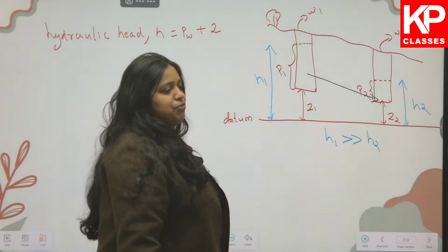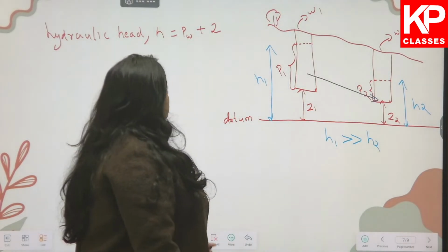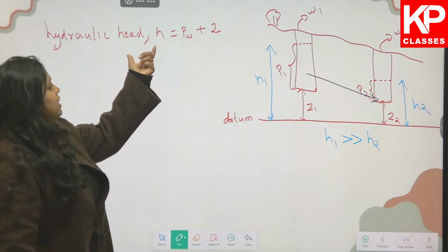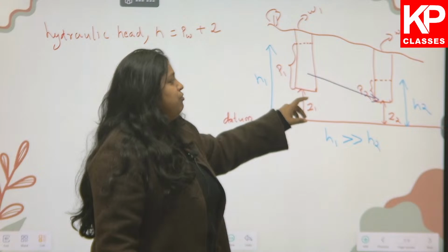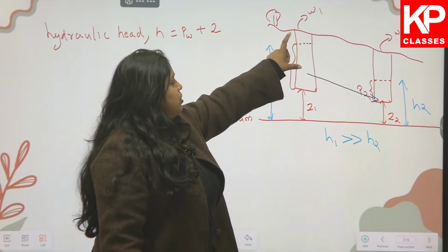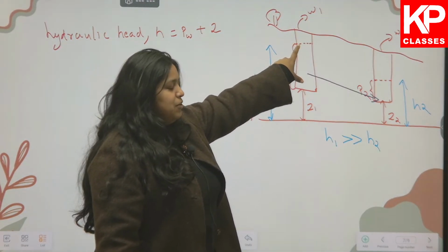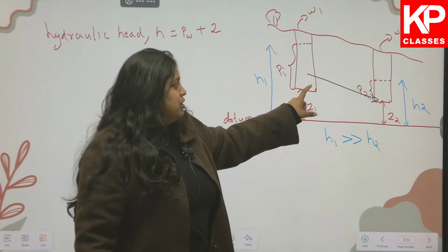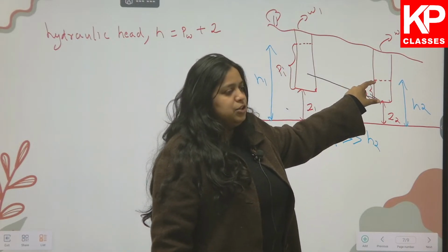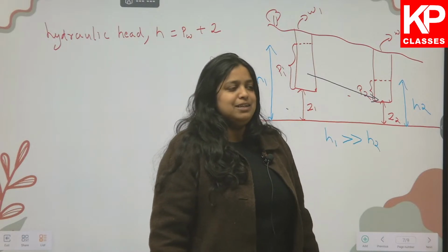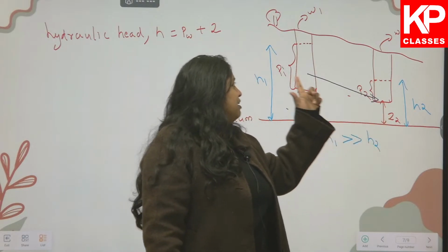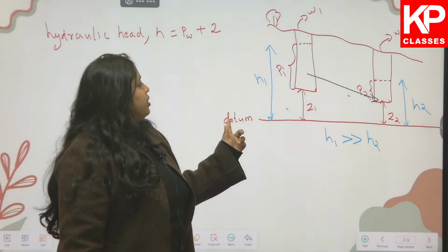So always remember, hydraulic head depends upon the summation of the water height in the well and the elevation. It is the sum that defines the hydraulic head.